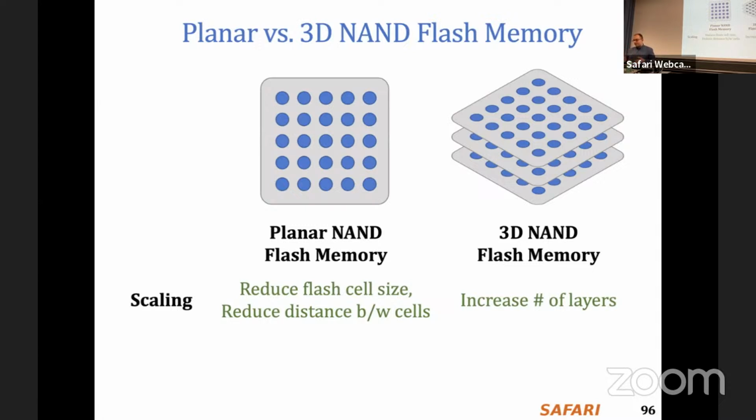The whole issues that we have with DRAM scaling, we also had that with flash memory. But fortunately, they came up with the idea of 3D NAND flash memory, and now they have another degree of freedom in order to provide capacity. So they could actually make the cell a bit larger, such that they don't have that many errors. But then they build cells on top of each other, in 3D layers. So with that, they provide both capacity and also better reliability.